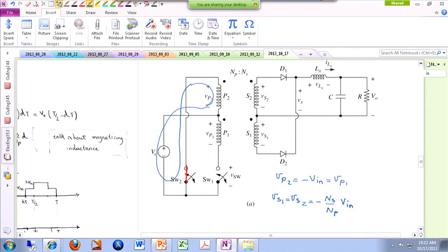So again, going back to our rectifiers, we have a center tap full wave rectifier. Now as it turns out, our voltage is negative, and if you remember, if the voltage was negative, D2 was the diode that was conducting. So we don't do that analysis anymore, I'm just refreshing your memory. Because this is negative, therefore D2 is on and D1 is off.